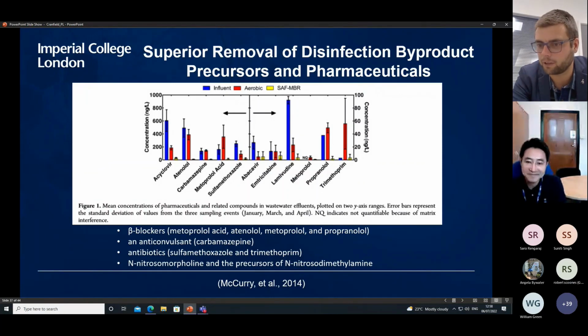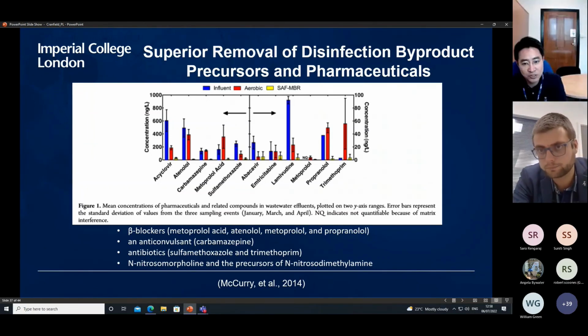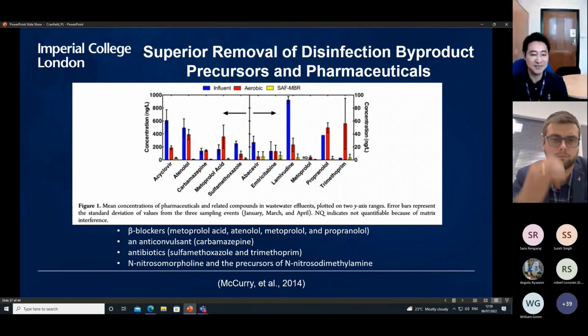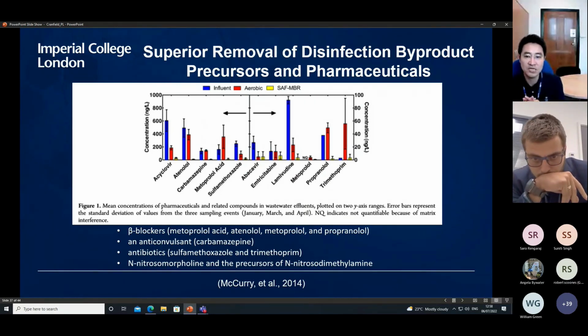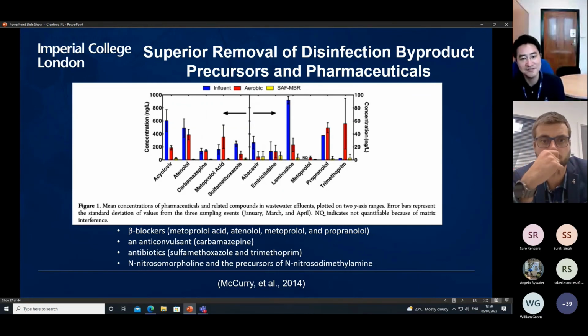Great, okay. And then we've got one from Vicky saying, did the lab scale have pH control with fixed or variable pH? And if so, is there any observable effect of pH on the biofilm? No, because the system is really efficient. We barely measure VFA, so the pH will be easy to control. We're never actually needing to control the pH. That's a beautiful part of the system, because you've got bacteria and they like the food. With Geobacter and Methanothrix, they all hang on to the acids, so the VFA is so low that pH will not be a big issue in the system.